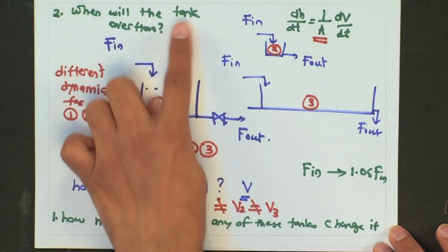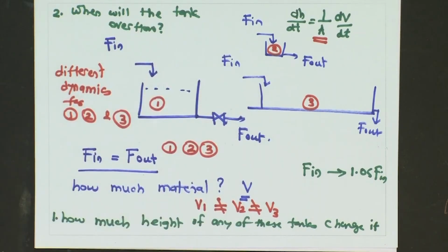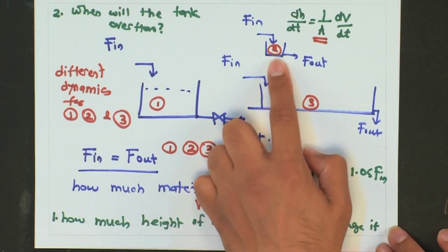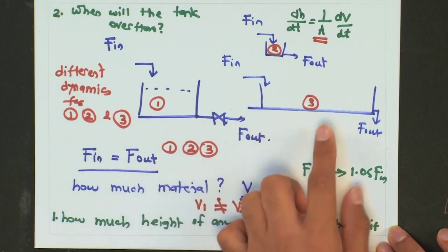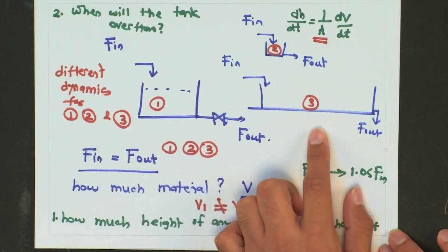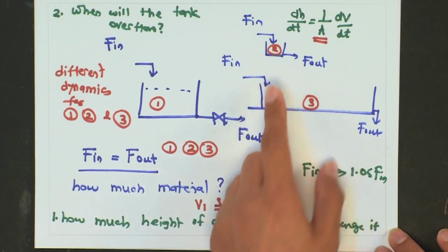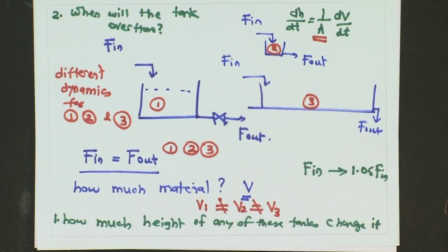So, when I asked the question what time would any of those tanks take to overflow, the answer would be the tank 2 would be the first which would overflow, followed by tank 1 and lastly tank 3, because the rate of change of height is the smallest in tank 3 and it is highest in tank 2. So, dynamic modeling gives us additional information about the system, and it is that additional information itself that is required when you design a control system for that particular process.